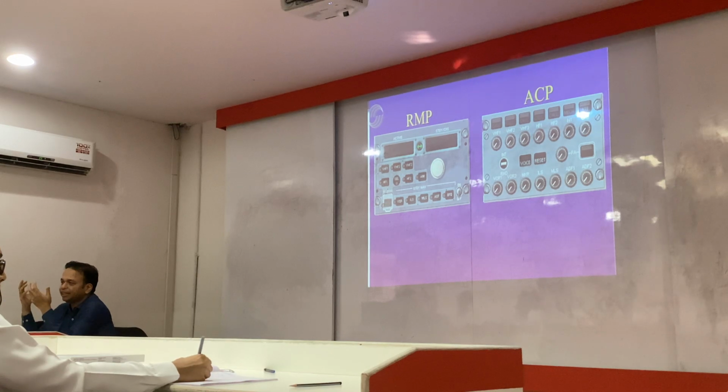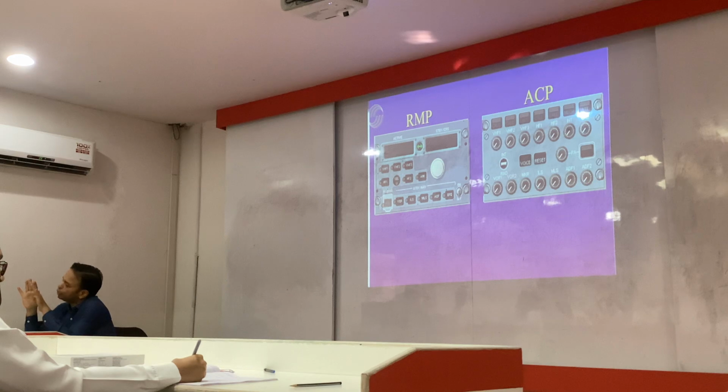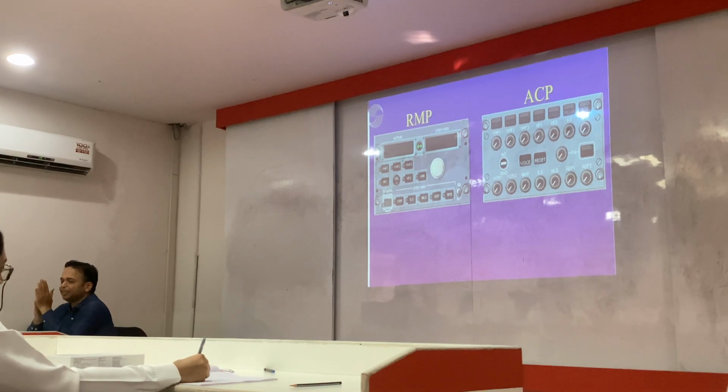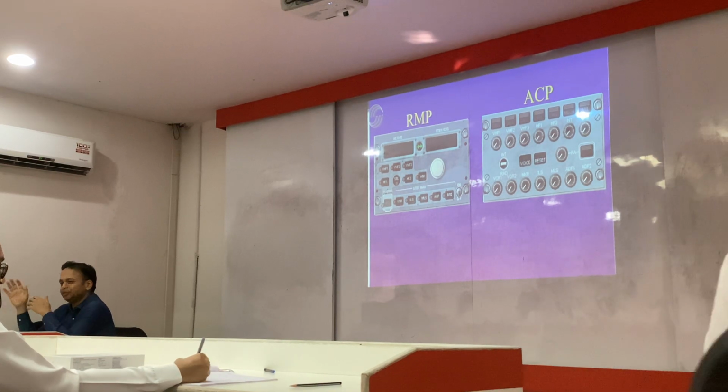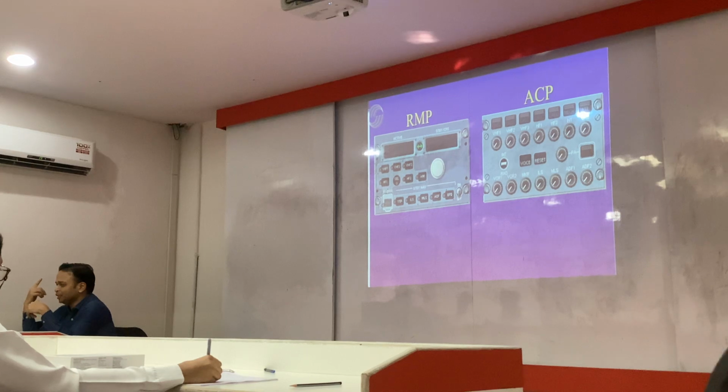Is there any onside radio which can be selected, or any of the VHF or any of the HF can be selected? Any of the regions. See, you can select anything. That is fine. But there is a dedicated channel. So suppose in RMP1, if you are selecting VHF1, it is dedicated to that. RMP2, you are selecting VHF2, it is dedicated to it. But you can select VHF2 in RMP1 and vice versa, as well as for RMP3. The only thing is that dedicated channel, nothing else.